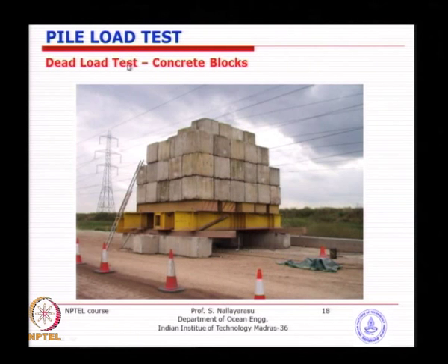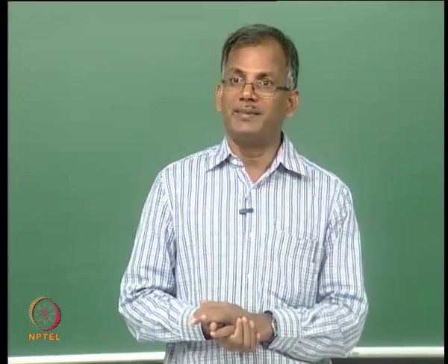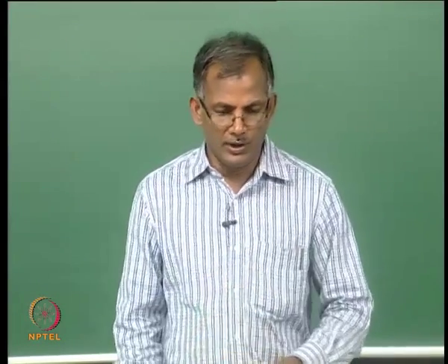Sometimes these concrete blocks will come with shear keys, so you can have an opening at the bottom, and when you place it, it will not go anywhere, and horizontal stability is well established. So, you can have a precast block specially for testing, not just for any other purpose.